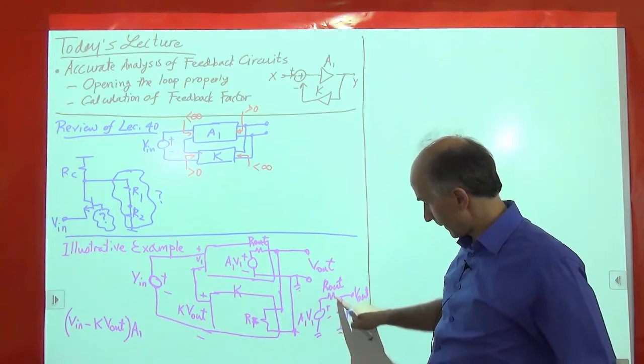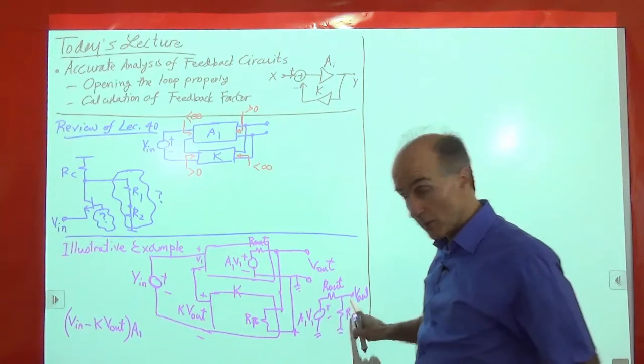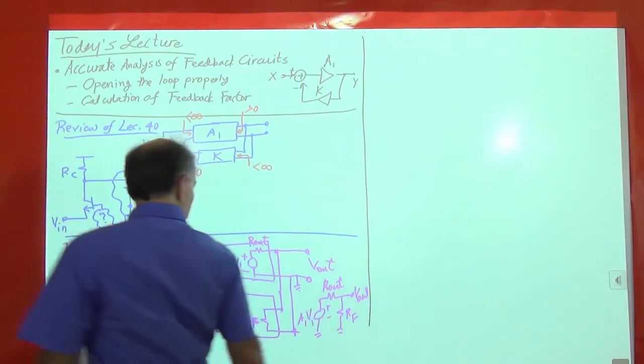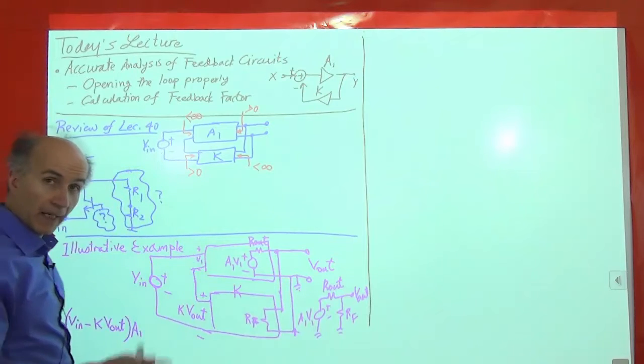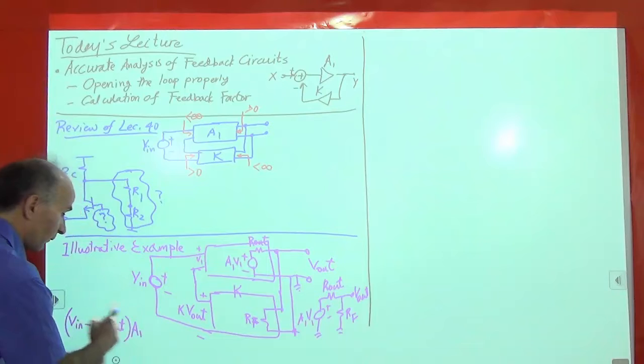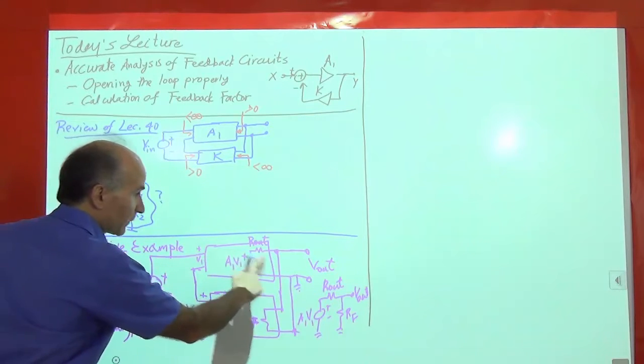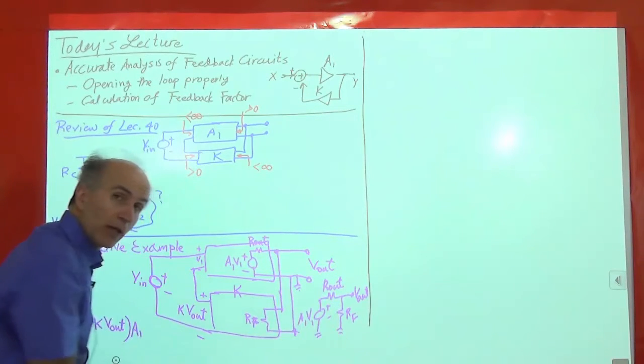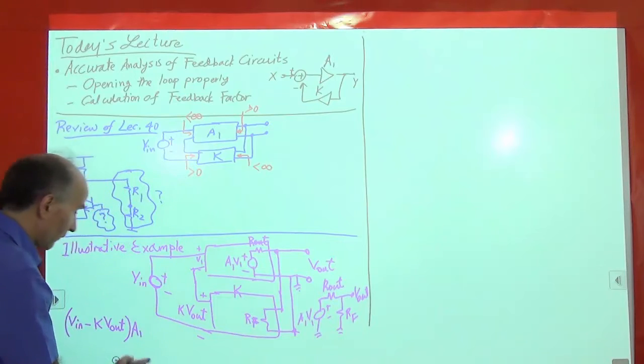So you can see what happened, right? We have a voltage divider. So V out is not all of this voltage, as was the case in the idealized scenario. This voltage that we have obtained has to be multiplied by this attenuation factor before it gets to V out.